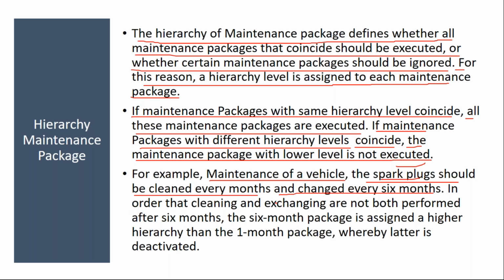Now, so that cleaning and exchanging are not both performed after 6 months, the 6th month package is assigned a higher hierarchy than the 1 month package, whereby the latter is deactivated. That means on the 6th month, anyhow you are going to replace the spark plugs, then what is the point in cleaning? So you don't clean on the 6th month.